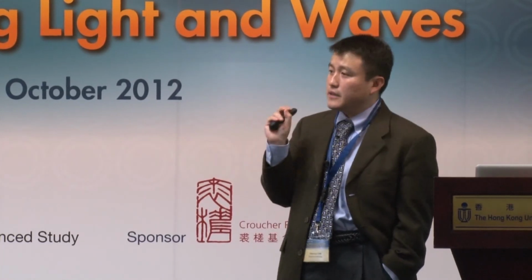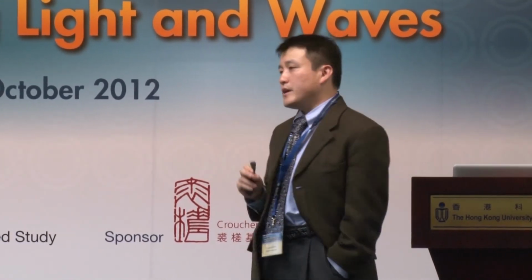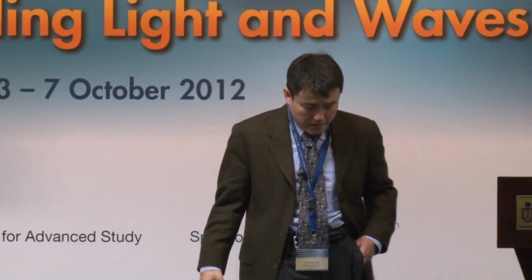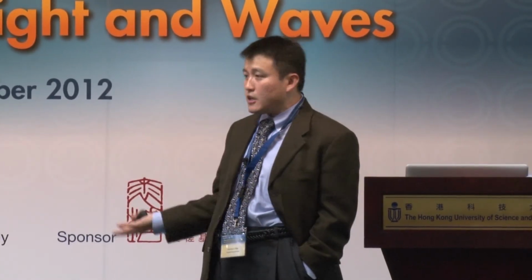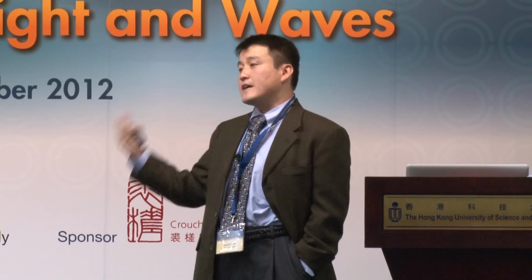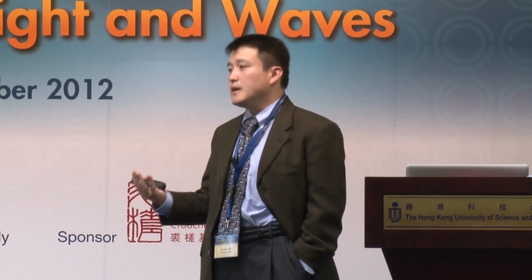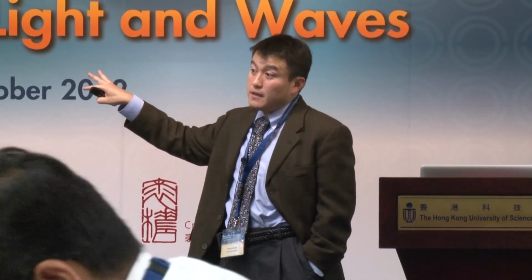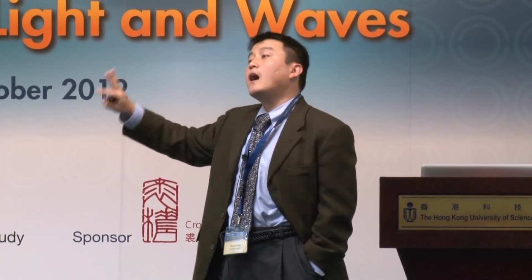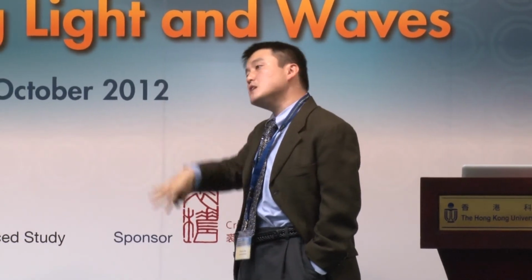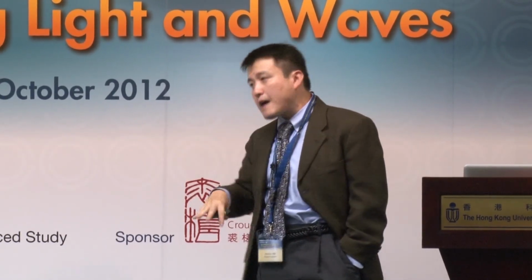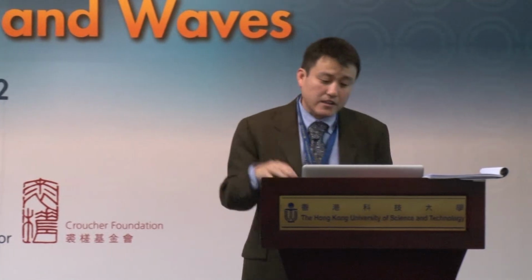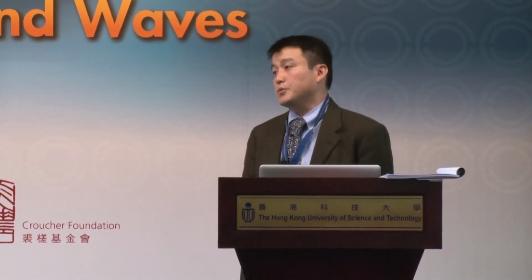The second point, I think, is the use of the isolator itself. It is certainly very important to prevent light from going back to a laser, because that gives you a laser stability issue. But what you come to see in many of the system designs that people do is they throw an isolator in whenever they have back reflection, even far, far away from the laser. And because you cut off the Fabry-Perot, you get a much better system. So from that perspective, it's not just an argument of protecting the laser itself. At least that's how I would argue.